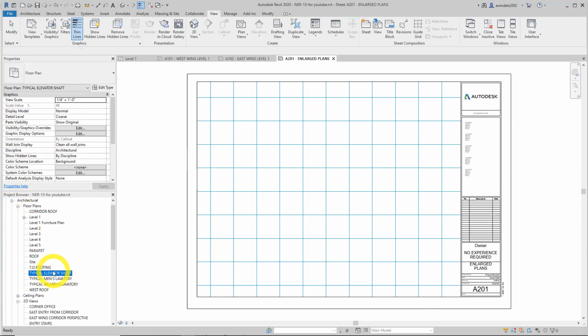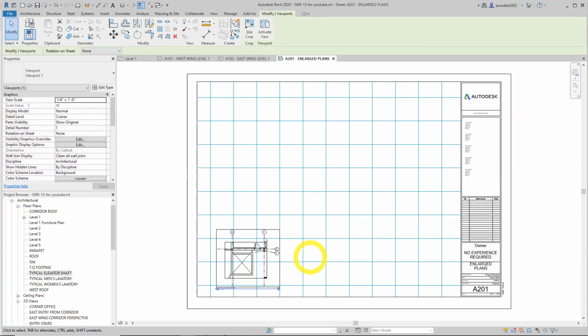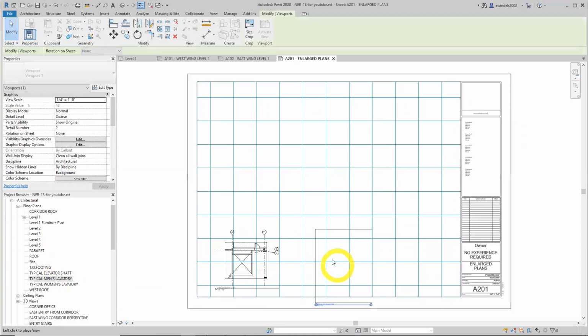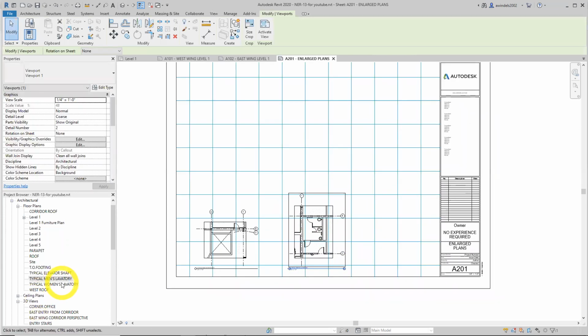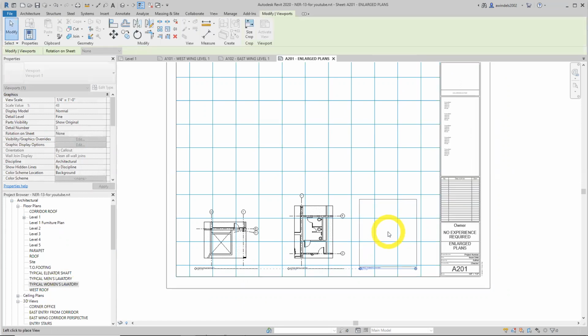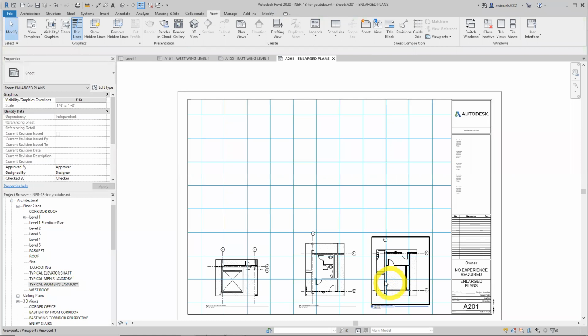And let's just populate them like the picture on 638. Got it right about here. As you see, when I populate these, they're going to line up together reasonably well. Drag and hold. And see my alignment dotted lines come in, which is really nice in Revit. It quickly snaps and has a smart sensitivity to that. And the last one, the women's lavatory. Right about here is good enough. Doesn't have to be perfect. So we got those placed.